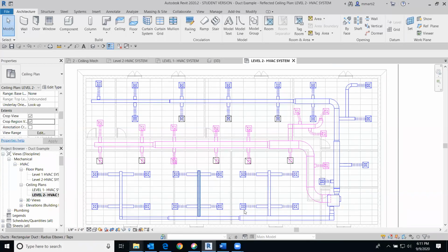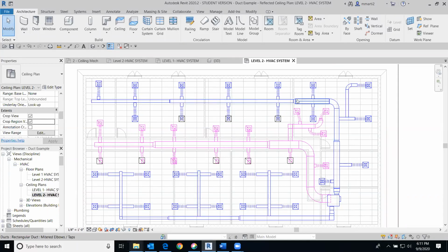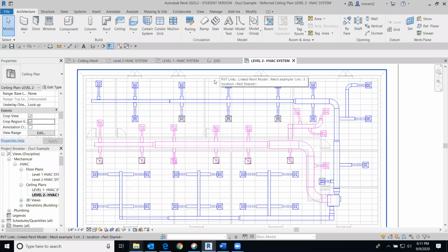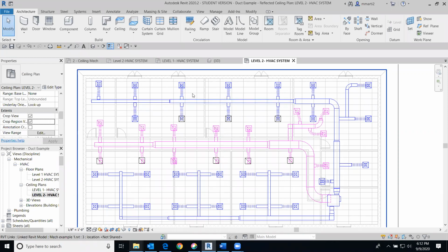So when you're laying out this new one, again, you can use this one as an example and have them laid out like this as smaller and constricted ductwork. The most important thing to remember is when we get to laying out the ducts that go into the individual rooms, these should be the sizes of ducts that you use for the calculations that you have created. Does that make sense?